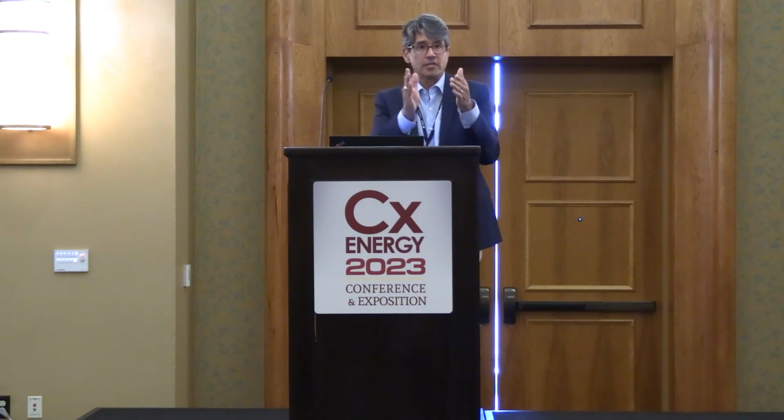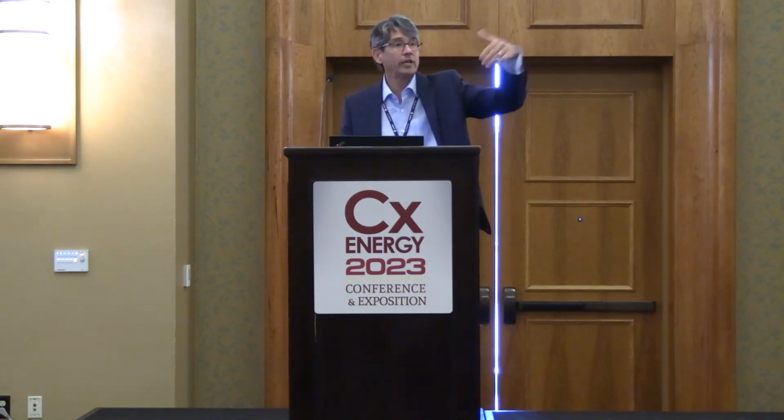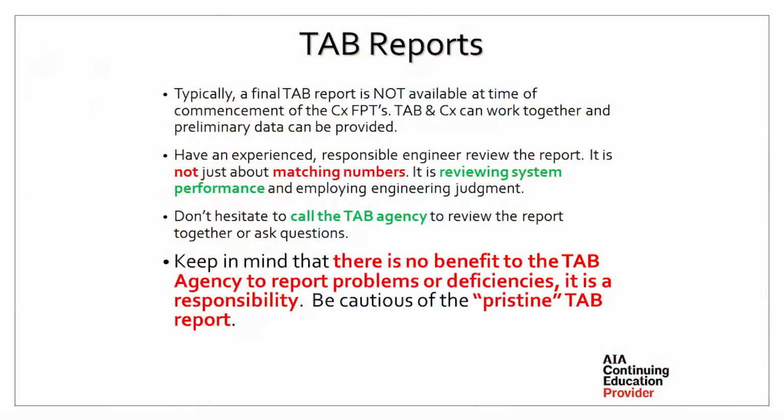You're really probably looking at putting branch balancing valves in possibly, maybe automatic flow limiting devices, but at least some sorts of methods to measure airflow going to those areas that are finished to try to figure out what you have and then what are you going to have after the next area is finished. So scheduled jobs can become messy. You're probably going to have to look at it. You might spend more time figuring out what do we need to do to accommodate the schedule.